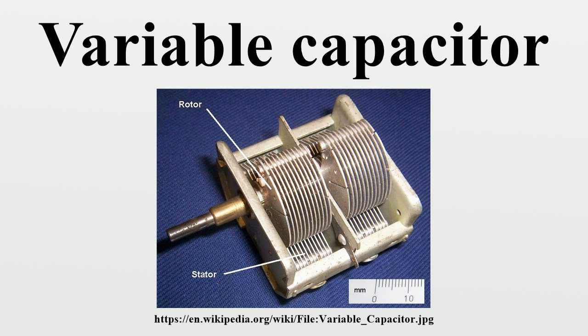SOI/SOS tuning devices are constructed as solid-state FET switches built on insulated CMOS wafers and use MIM caps arranged in binary weighted values to achieve different capacitance values. SOI/SOS switches have high linearity and are well suited to low-power applications where high voltages are not present. High voltage endurance requires multiple FET devices in series, which adds series resistance and lowers the quality factor.